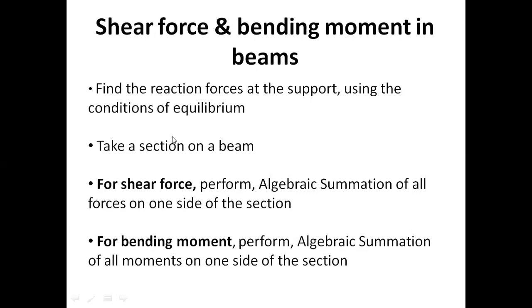So in order to solve the beam problems, or in order to draw the shear force and bending moment diagrams, first of all we have to find out the reaction forces at the supports using the condition of equilibrium. Then we have to use the section method. So depending upon the type of loading, we have to take a number of sections.